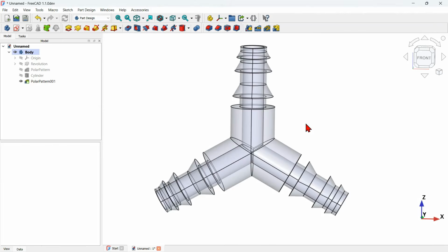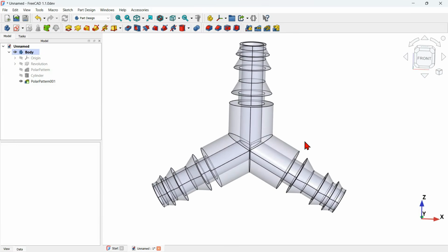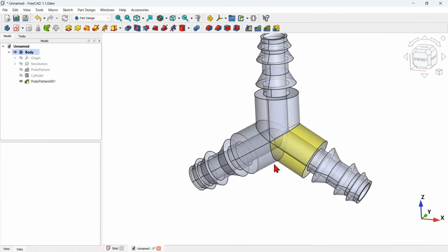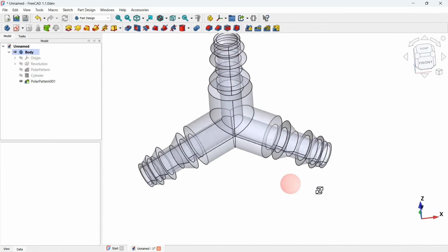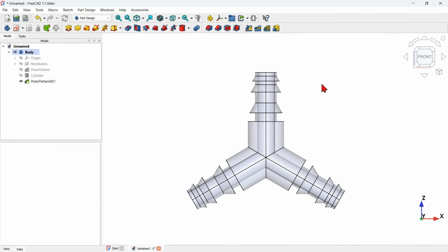And this is how you should proceed to draw this 3D model. You should leave the hole for last. If you had created a geometry for the hole directly in the sketch, you wouldn't be able to achieve this result here that I have on this document because of how the 3D model is laid out. I'm sure you get the idea. So now I will show you an example. I will change to the front view, so this way you will see clearly what happens here.